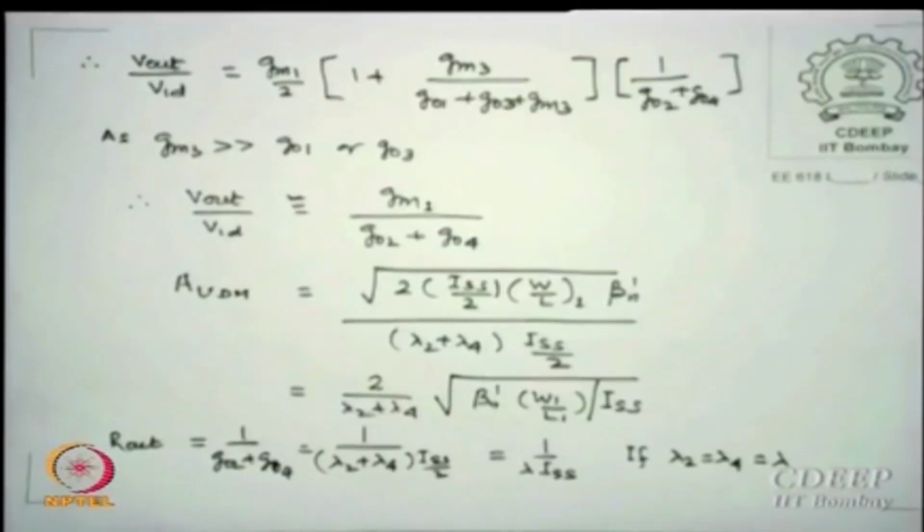Okay, is that clear? So this is essentially what we are doing, and therefore we say that this V by V only tells input is voltage and output is also voltage. Okay, so I did not write it, but I just thought you should know that in many books or many places the data sheets give V by V. So what is V by V? It is trying to tell you it is the voltage gain dependent terms which have been specified. Sometimes they may write V by I, I by V, I by I. So these are the methods of representing the amplifier outputs or gains.